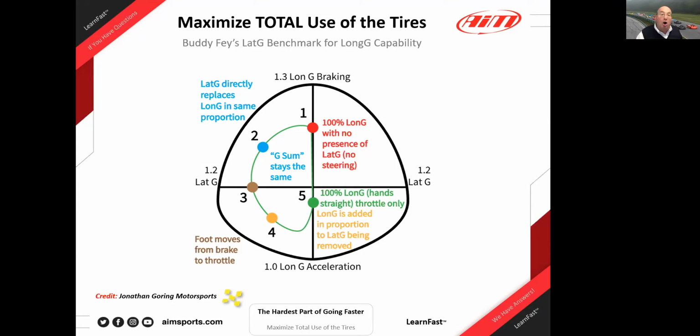If you had R-comp tires, so Hoosier R7s, Toyo RRs, these other sticky tires, Yokohama Advans, not slicks, but DOT tires with sipes and treads and stuff, it should be 95%, required by a lot of the racing classes. So 95% of the maximum braking facility should be available in left or right turns.